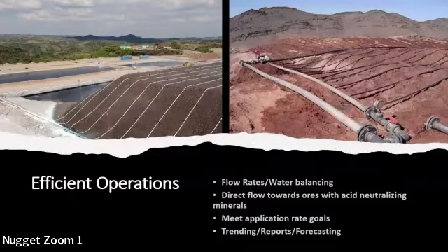Particle size distribution, to understand what the gravel and fine content is in there. And then clay speciation, looking at XRD analysis. So, are there swelling type clays in there? There were some other physical property measurements we performed, particle specific gravity, some Atterberg measurements and so forth, but I won't go into that in this presentation.